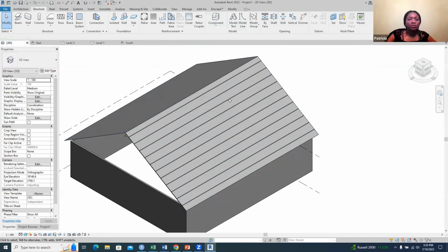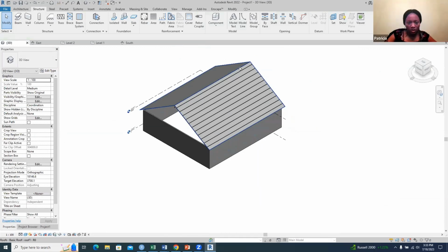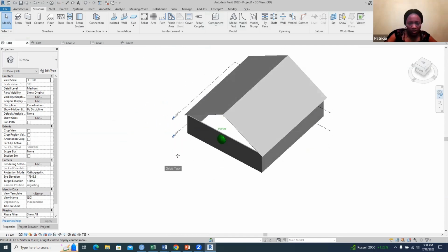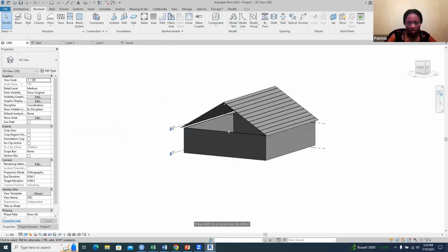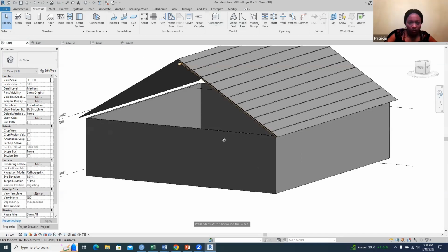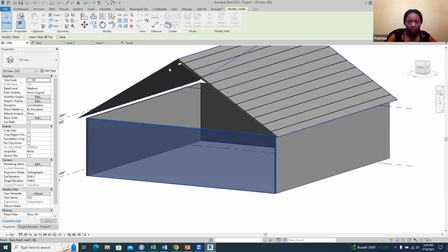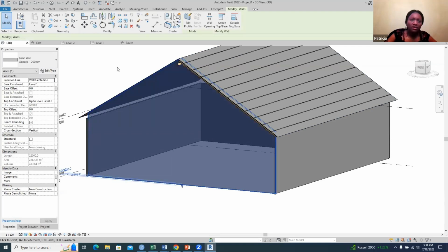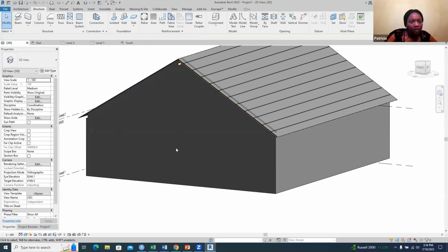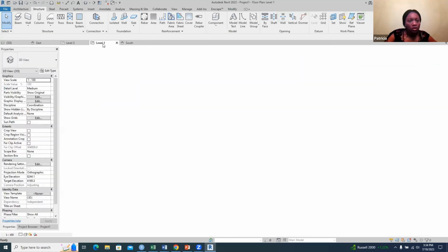So let's go to cutting walls. That's the second one I want to look at today. So if you want to move it around, pick a center and then move it. So we use this part of the roof. Let's attach it to the top, and then if I select this, attach top to here, that attached. So let's make the cutting wall. I'll go to level 1.